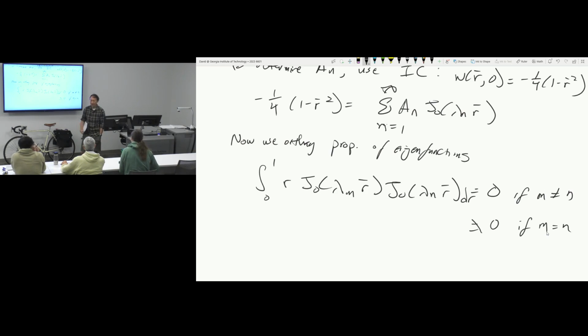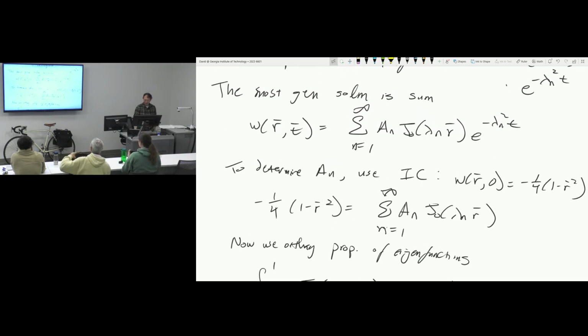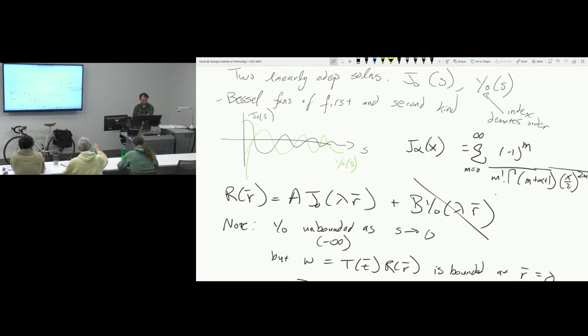Once we solve for the velocity field, you can figure out the shear stress anywhere by taking du dr. A solution W looks like this, where you have this exponential function of time, and this tells you what it looks like from the wall. It only goes at the wall, r equals n. The one we actually care about is going to be something like here, S equal to 1, I'm guessing. I don't remember what the scale is. But it's going to be all the solutions in that space. You could probably just take the first 3 or so if you really wanted to calculate something like this.